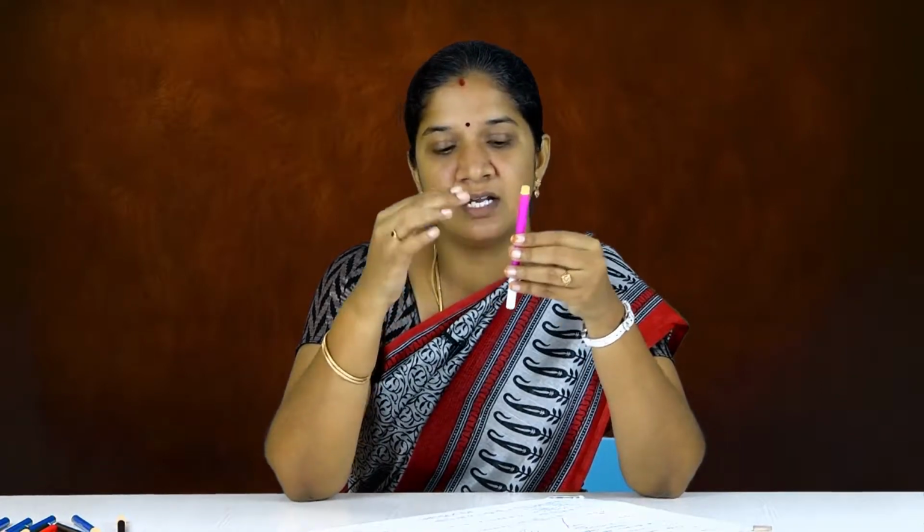A doubly reinforced section is one that provides reinforcement in the compression region and also in the tension region. Why is it so? Why do we need to provide two layers? First, while designing your beam, you need to check whether the actual moment for your beam is less than your limiting value or greater than your limiting value. That limiting value we can call Mu limit.